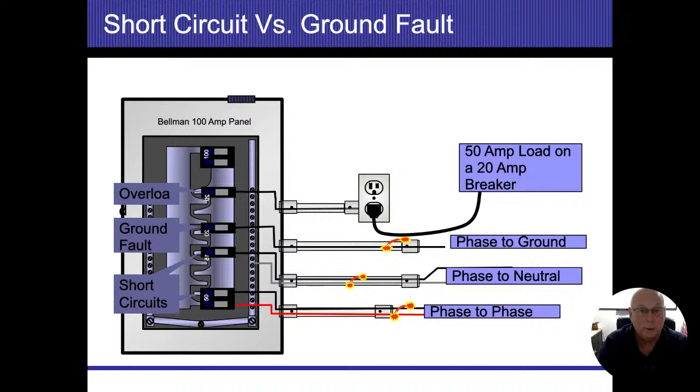So if my conduit is energized, my box is energized, that bonding screw is energized, and that bonding screw is connected to my neutral bus bar, now my neutral wire is energized. Now I don't have any sort of resistance at all. Whatever's available on the system will attempt to flow, far more than that 20 amp breaker, far more than the 100 amp main disconnect. So those should trip right away. And even if they don't, then we're going to get a burned up wire, which will actually break the power as well.